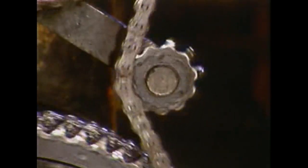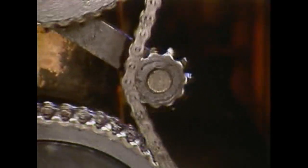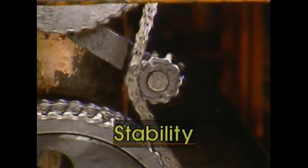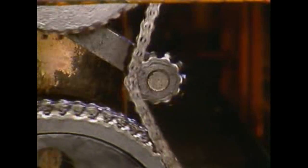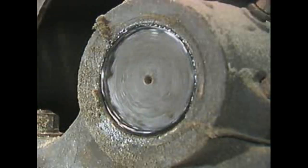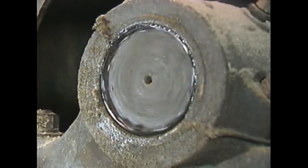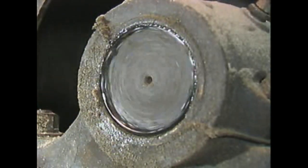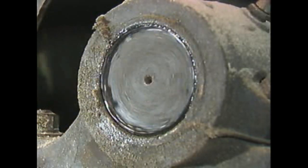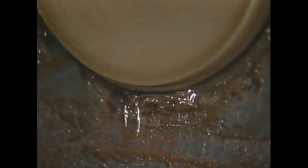The ability of a grease to retain its chemical and physical properties when subjected to extreme temperatures or exposed to reactive substances is referred to as the grease's stability. In many applications, it's crucial to use a stable grease to protect the equipment that's being lubricated. Bearing applications are especially sensitive to instability. If the grease in a bearing breaks down from the heat that's generated during operation, the grease will leak out and leave the bearing dry, causing the bearing to seize. A stable grease, on the other hand, resists breaking down due to temperature increases or exposure to air, water, or reactive chemicals.